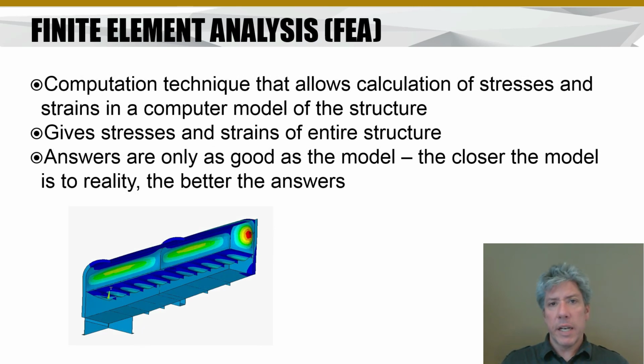So finite element analysis is something you've heard me talk about. It's a computation technique that basically breaks a body down into a lot of really small parts, assumes there are springs between them, and then calculates, given a load at one point, how much each spring would stretch. And what's nice about it is it actually gives you the stress at every point within the model. Now, a lot of times, the finer the mesh, or the more elements you use, the more accurate results you get, but also the longer the computation takes.